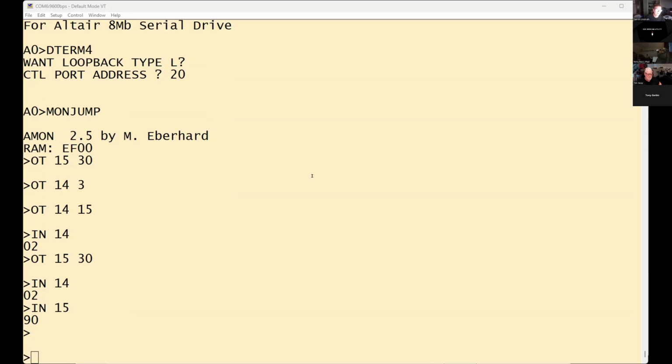But he says it works on the other computer, so it has got to be a cabling problem. Yeah. Or something interfering. Well, the thing is, if the console's working, then it's not the normal handshaking lines they all share. I'm trying to think of anything on the bus that could cause this. Well, like I said, the UART isn't receiving the data. Yeah. Otherwise, that status bit would go up.